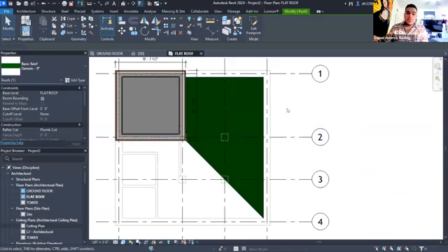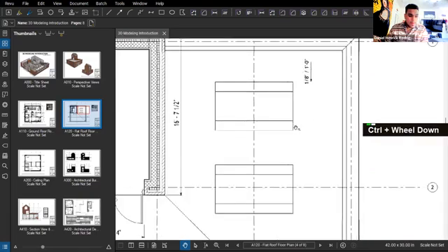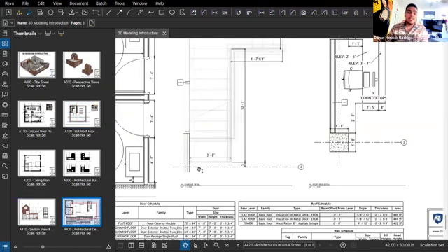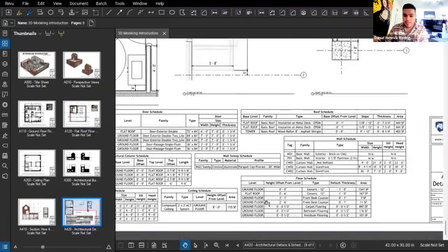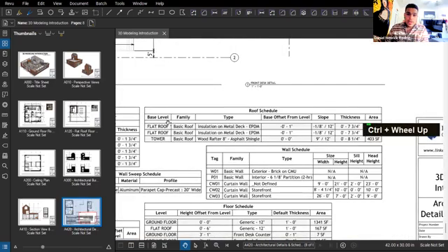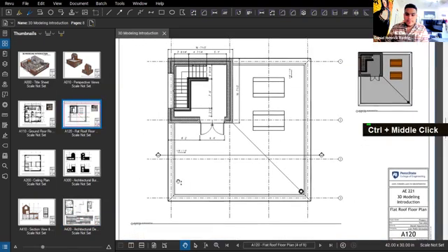All right, so we created one. Oh, my mistake. And you guys might make this mistake as well. I didn't see what type of roof it was. I just put it down. So let's go back. And this is not an issue. In Revit, you can go ahead and change everything. So we're gonna go to our roof schedule here, and we have the 2 individual flat roofs, right? There are 2 because they have different slopes. So you build one, and then you build the second one.